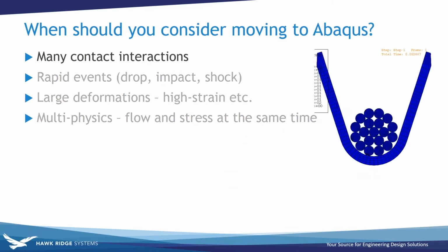And the first one there is contact. Anyone who's set up a problem in SOLIDWORKS with a large amount of contact knows how difficult it can be. Not only do you have to go through all the trouble of selecting all of the faces you need, maybe splitting the faces to make sure the contact goes through, it can also be difficult to get the solver to run if you have a large amount of contact.